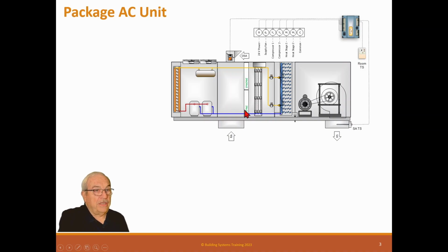It could be there's a leak and no refrigerant in the system. It could be the filters are totally plugged, there's no air coming down the system. It could be a lot of different things. But at least you know it's not working, and then you can send a technician up to figure it out. That's why we use those status points.